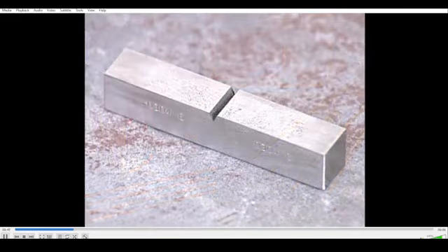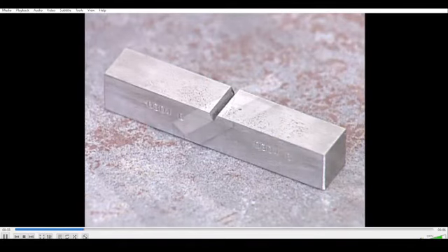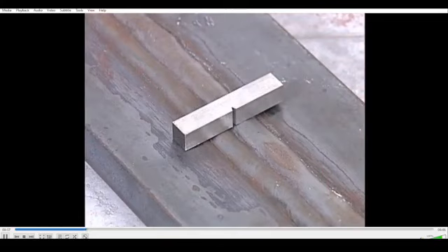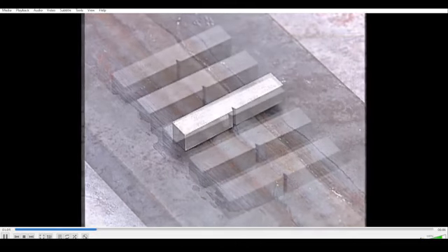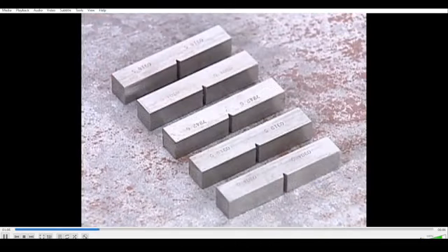The most common form of impact test is the Charpy V-notch, so called because the specimen is prepared with a precisely machined notch. Specimens are removed from the test piece transverse to the axis of the weld, that is, across the weld. Usually a series of specimens is removed, the number depending on the applicable quality specification. Normally 5, 7, or more are required to properly determine impact properties.